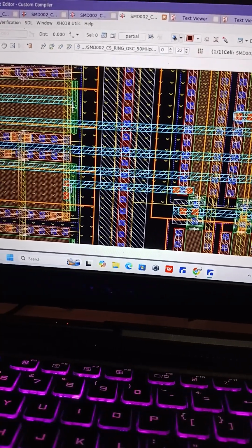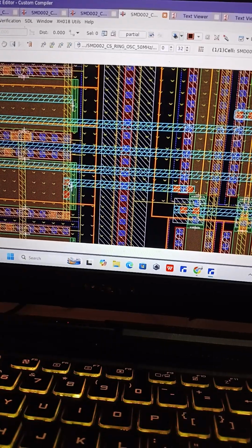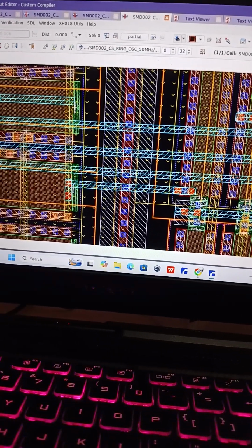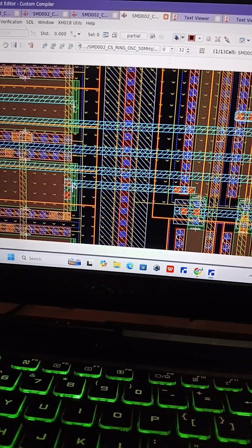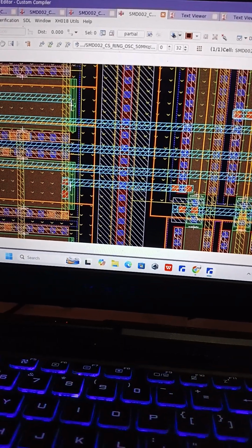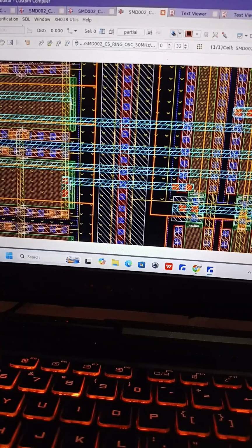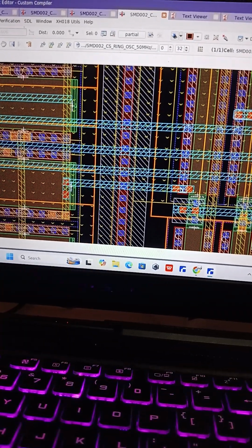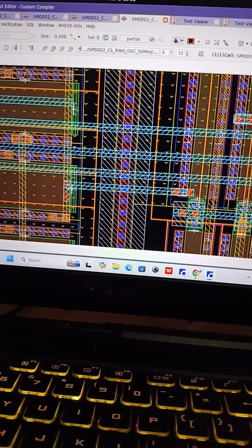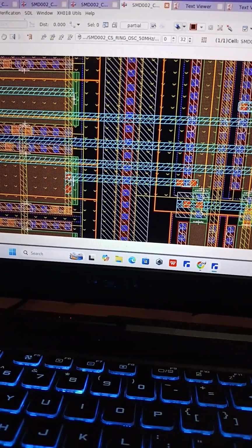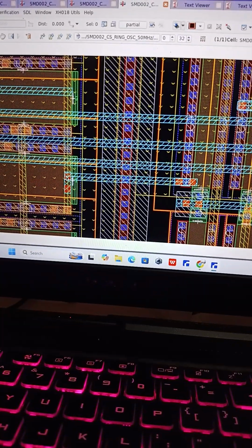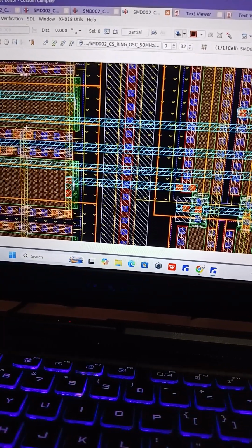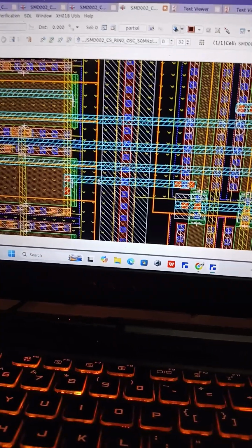So this must be lower than 10, because this has resistivity properties which induce resistance. Here 10 volt, this might be 9 volt. So the drop is about 1 volt, right? Of course this is not ideal. So that's why there will be a parasitic resistance.